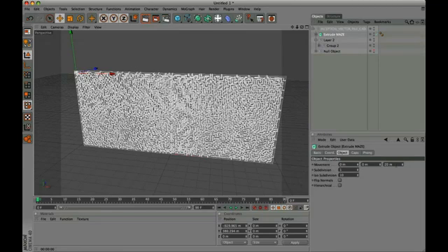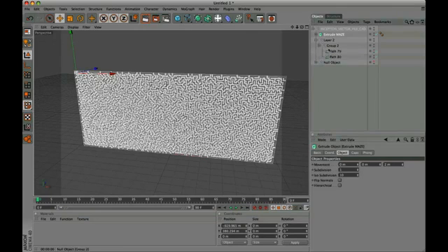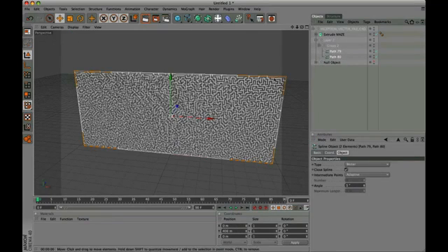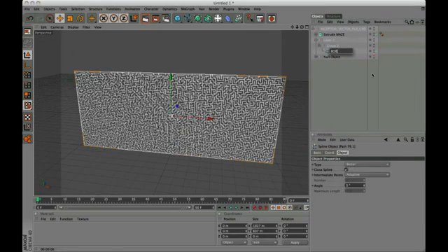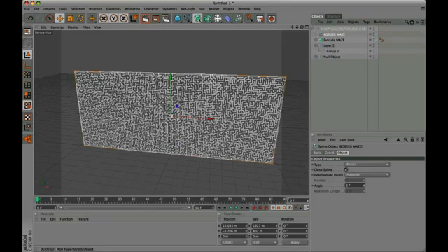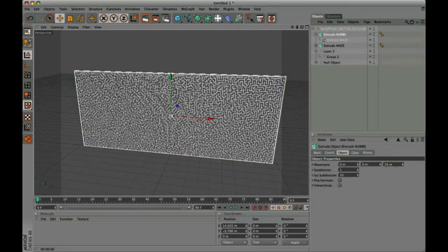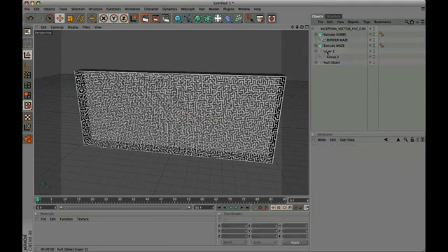We apply a depth of extrusion from 20 to 2. We select the 2 splines in the group 2 layer and merge with the command Connect plus Delete. Rename Border Maze. Drag it out and apply an extrusion with value 150. Delete the group 2 layer and 2 layer.